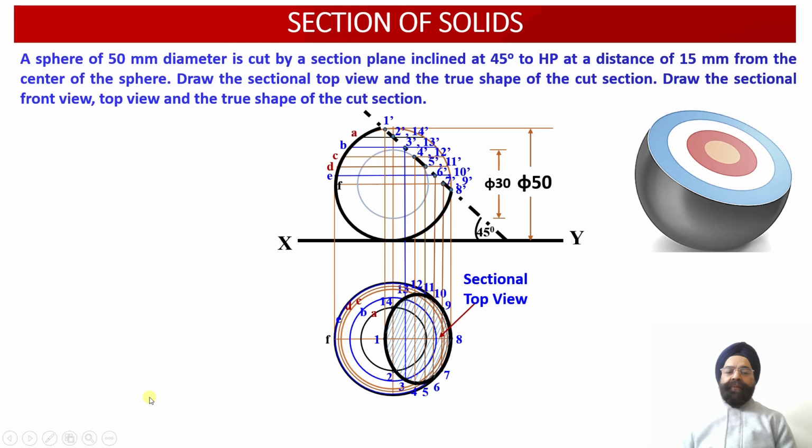So this true shape we already know, but we have to just verify that whatever true shape we are going to obtain, it should be a circular cut section true shape over here. So in order to obtain true shape of this cut section, observer will be looking at the cut solid into this orientation. Now we are required to draw an auxiliary inclined plane x1 y1, which will be parallel to this cutting plane or the cut section over here.